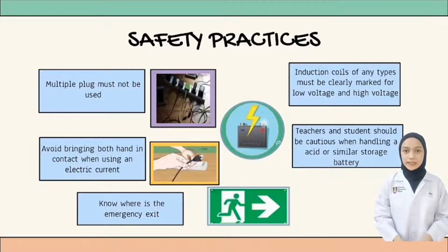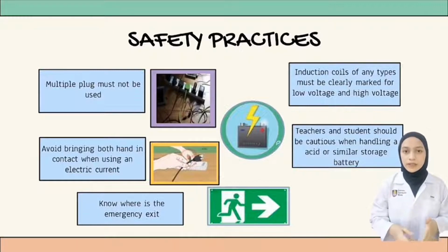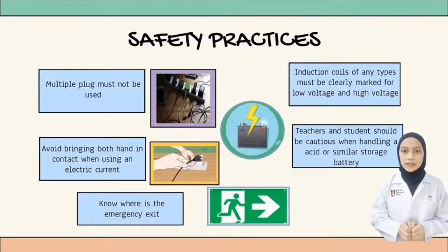Students and teachers must also be cautious when handling acid or similar storage batteries. Batteries can be menacing when mishandled. These batteries are large and heavy objects that can cause severe injury if dropped, and battery acid is corrosive and can cause acute burns to skin or corrode equipment when it comes into contact with it.